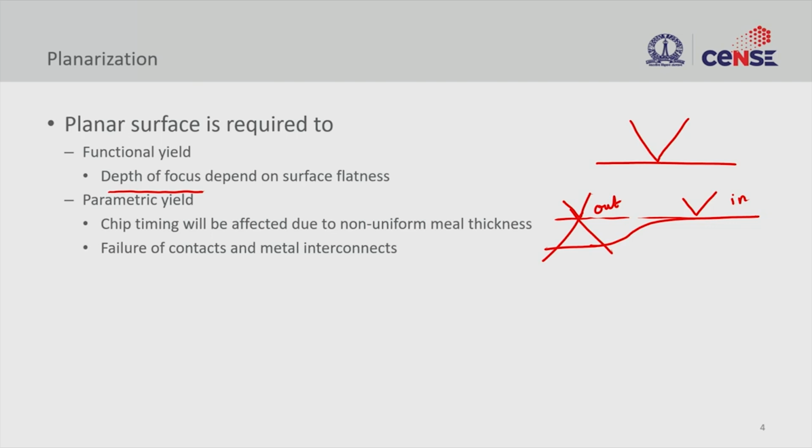So, if you have multiple metal lines connecting different transistor blocks or different functional blocks, if you want to transmit and receive data that is synchronized, if you do not have the uniformity, you are going to have timing errors, right. It will be very difficult to adjust. So, we want the metals to be uniform in cross section. So, for that you need a flat surface.